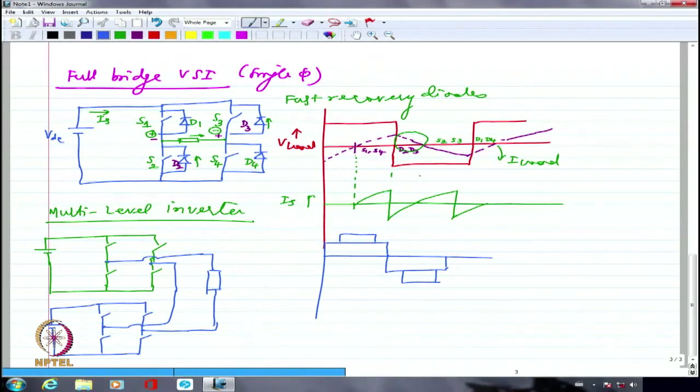So this will allow me to get twice the voltage of whatever is the voltage that I am applying here and here. But please note, I have drawn two independent voltage sources. I can't connect them also together. Either I need to provide isolation on this side between the two voltage outputs, or I need to provide isolation on the input side. Either on the input or on the output, I need to provide isolation. Otherwise, it will be a dead short, right?